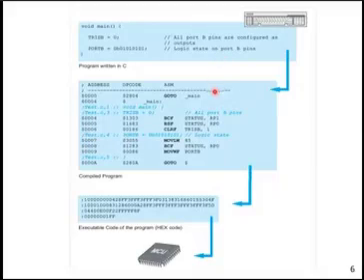If no error is detected, it will transform the C language, to be precise, first into assembly language. If you don't know, this is assembly language. And once the assembly has been generated, it will continue generating the hex file. This hex file will be burned, embedded inside the microcontroller using a programmer.